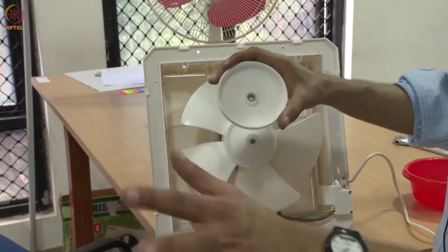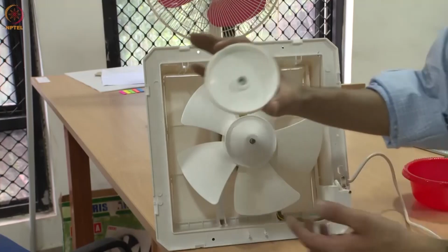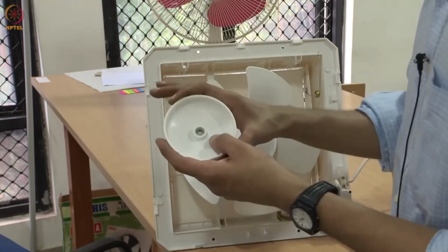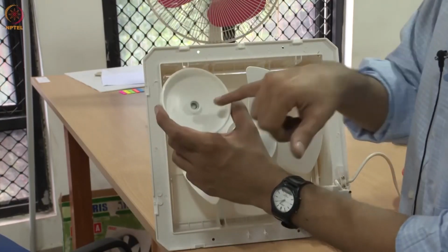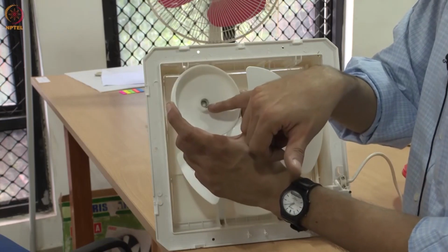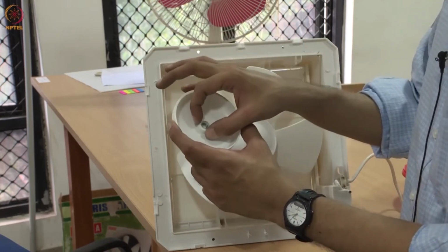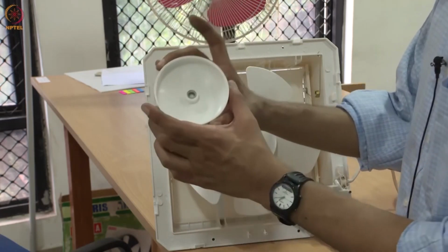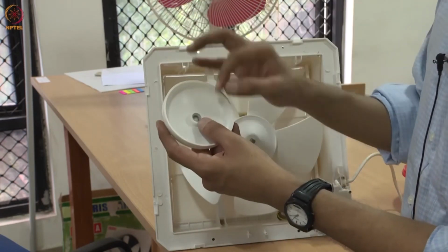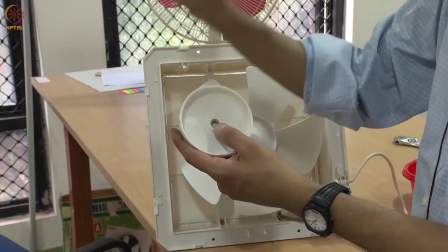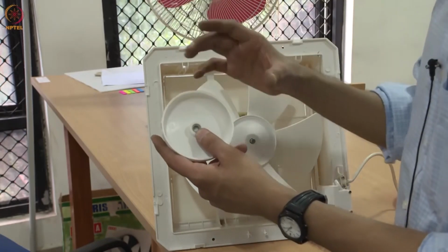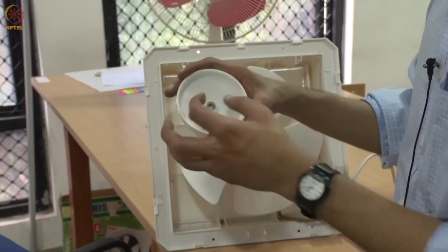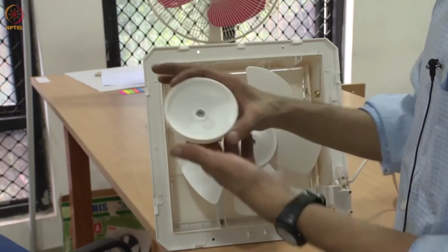So how is this manufactured? You have a metal insert, in this case a bolt that is made as an insert within the main component. They keep the bolt in the die and then inject molten plastic to entrap the bolt in place. That makes it into a single piece.